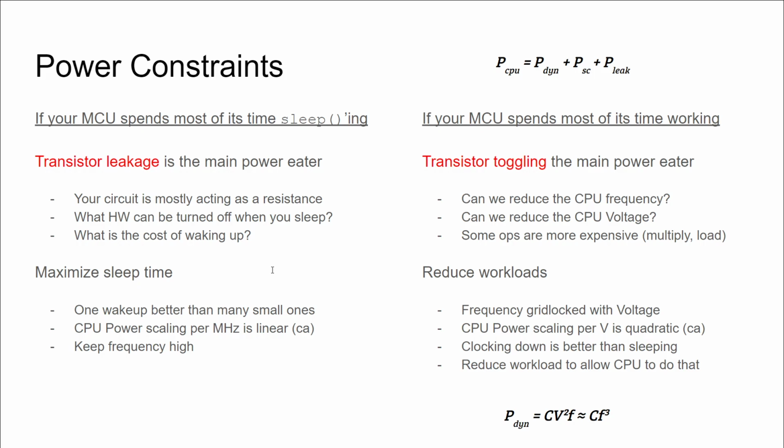To reduce power usage, you want to reduce the frequency. It's that easy. But by reducing the frequency, you're also taking longer time to run. In the case of the Angry Birds game, you don't want your per frame CPU workload to take more than one frame. So if the Angry Birds game is expecting to run 60 frames per second, the CPU workload needs to be done in less than a 60th of a second.